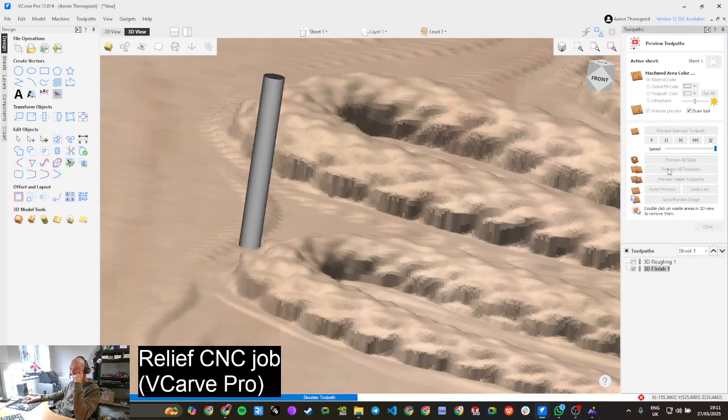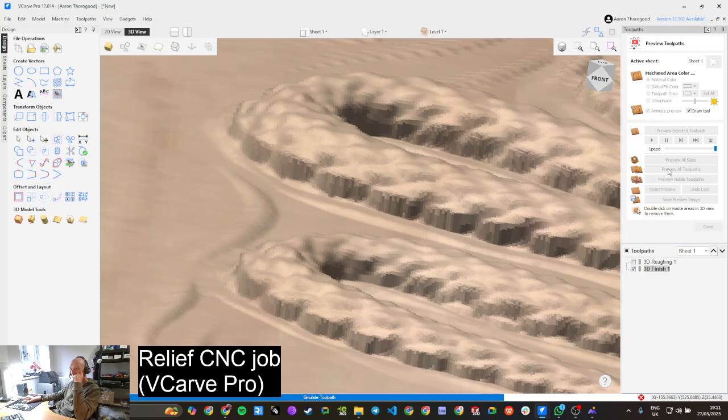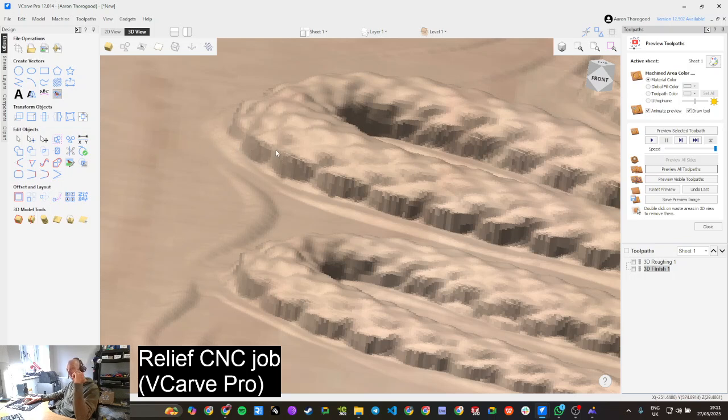Might not have anything at this stage. Oh, okay, yeah, it does a little bit. Yeah, that was worth doing. What it's doing is basically it's 10 millimeters away from the edge of our mesh, and then that's de-chunking quite a lot of stuff. I found that if I didn't do that, you would end up with lots of artifacts left from the roughing pass. So now that's done, we are finally into our